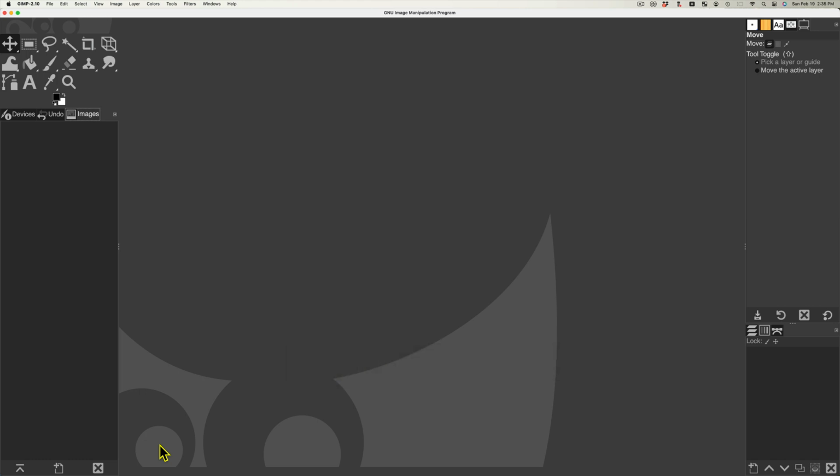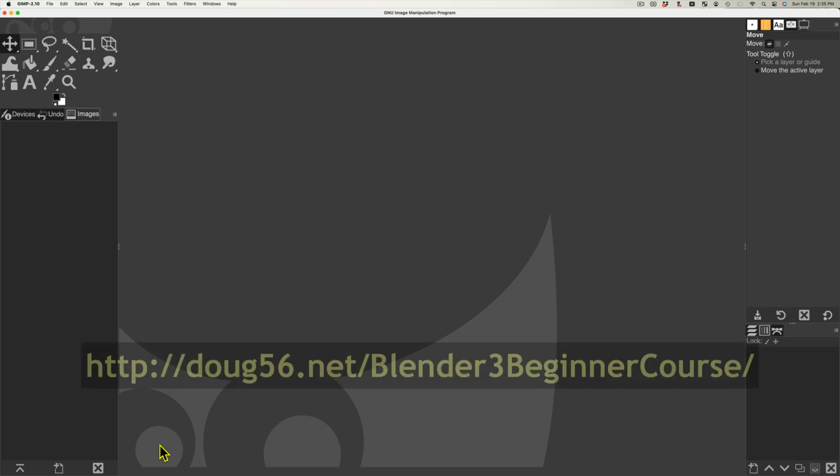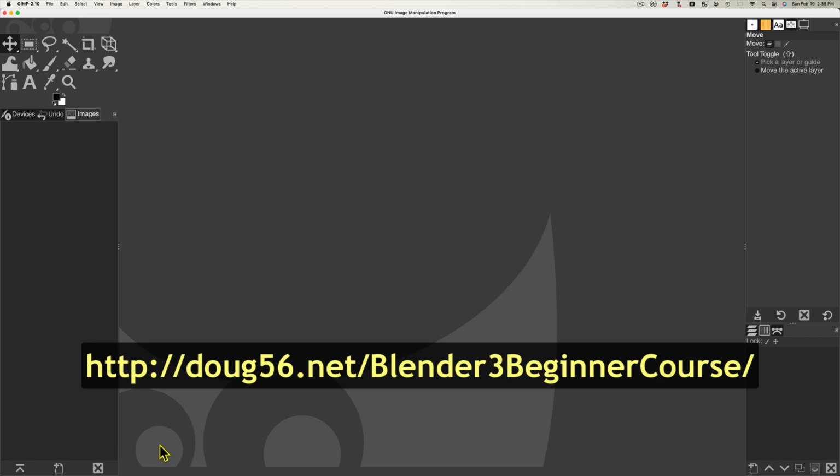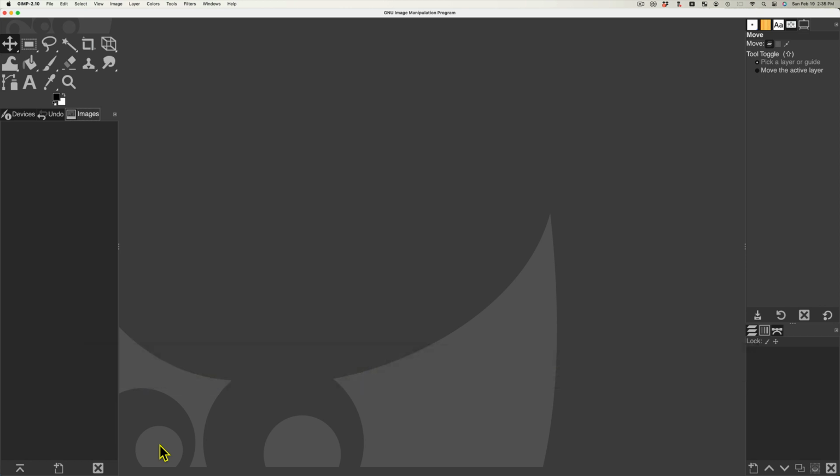To construct the bench in Blender, we are first going to clean up an image of an end in GIMP. Select an image from the internet, or you can use the one provided here. Images usually come in pairs, so we will first crop the image to isolate one end. Open GIMP and load the image.